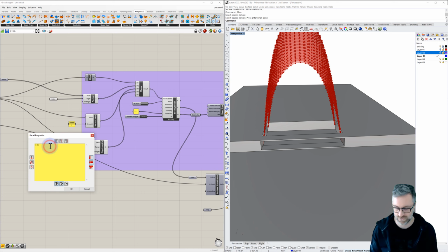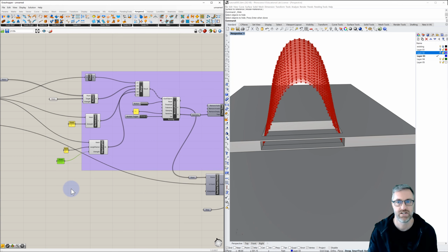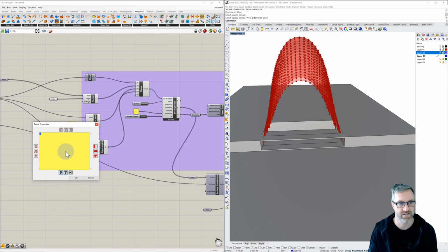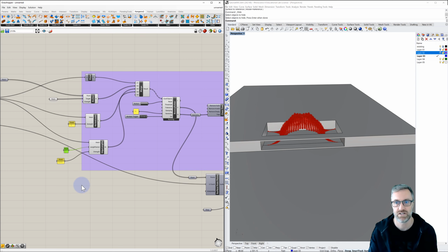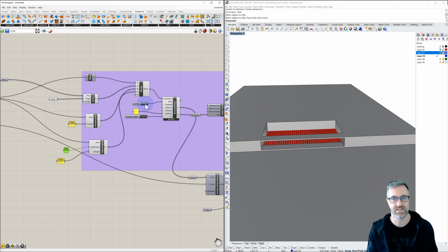Let's add another 2 zeros. Should bring it down. Not by a lot. So let's go back to the length factor and set that to be maybe 1.1. Just got deflated quite a bit. I'm going to hit reset.